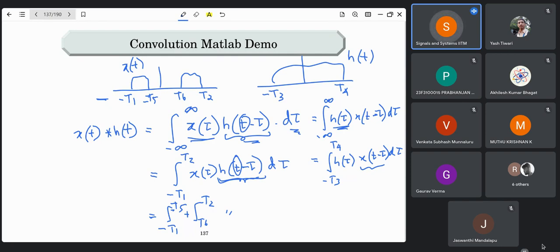It makes more sense to use Laplace transform for real-life signals, for causal signals, whereas Fourier transform could be used to analyze non-causal systems also. When you are designing a system and you want to optimize it, let us say you don't worry about the causality, it means you are not really worried about how to implement it, but you just want to know what the optimal system is. In that case, you use Fourier transforms, because they can give you systems which are even non-causal. Whereas Laplace usually is applied only for causal systems.